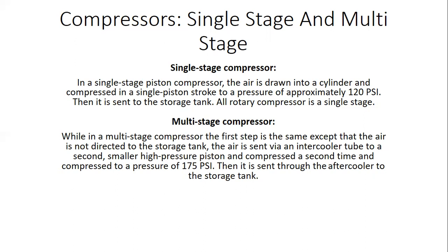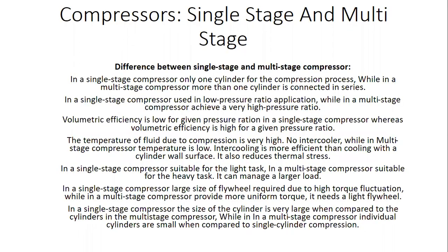Understand the process here. A multi-stage compressor involves a more complex kind of operation. The same thing that happens in a single stage happens in a multi-stage. However, instead of being sent to a storage tank like the single stage, it is sent via an intercooler where the air is cooled down a bit to another container or another area where there is a high pressure piston working on it that will compress it a second time to about 175 psi. Then it is sent via the aftercooler now to the storage tank.